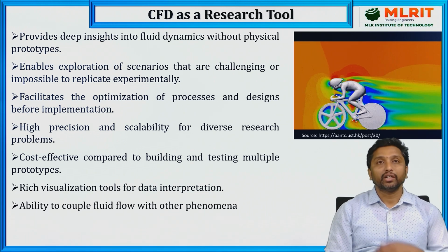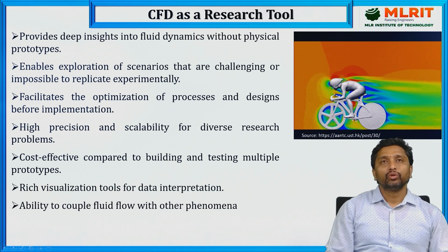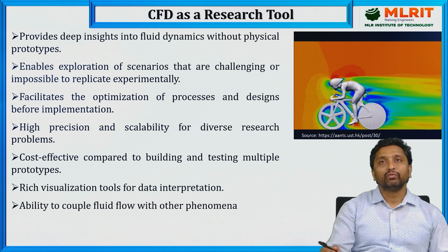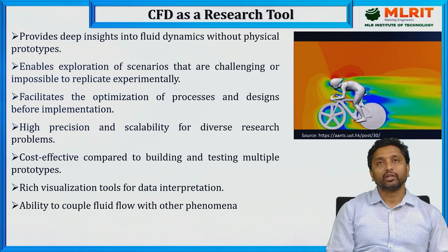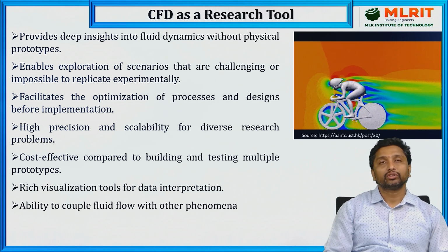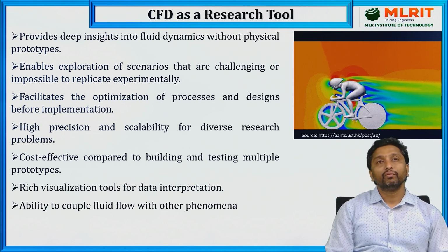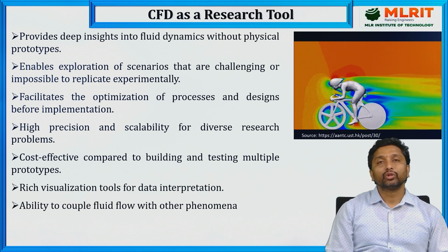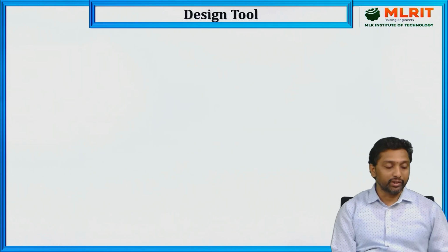Then we have understanding of multiple effects like fluid structure interaction. Unlike the experimental setup, where either a flow analysis setup or a structural setup is required separately for conducting flow analysis or structural analysis, in CFD we have something called fluid structure interaction, where we can couple the effects of fluid flow on the structural design. So coupling is possible in CFD. So let us come to design tool.